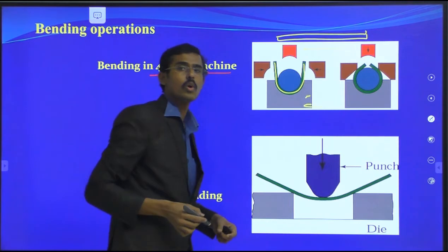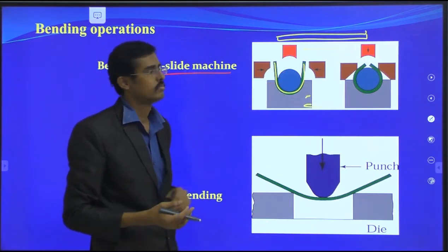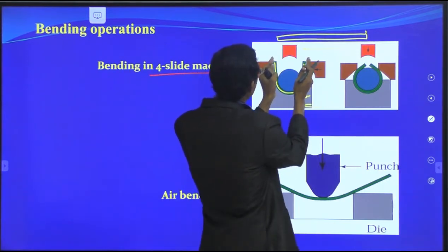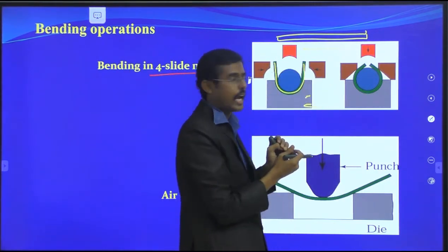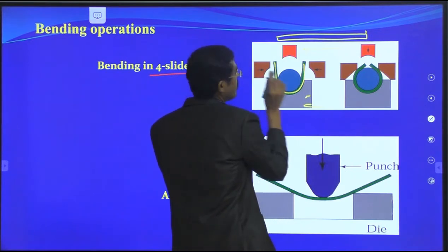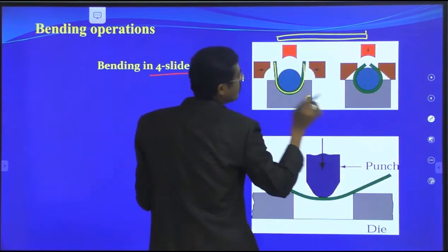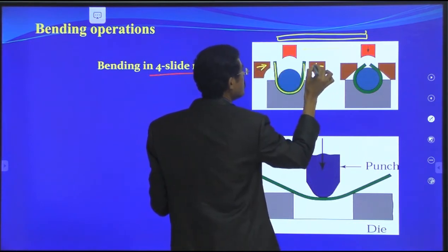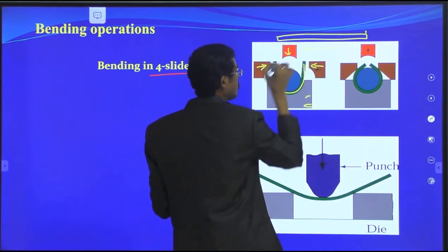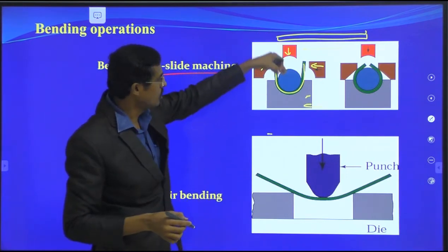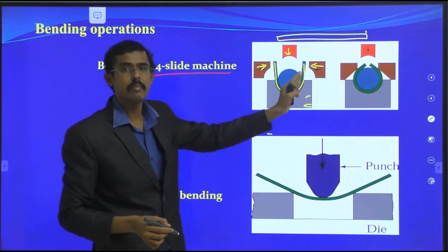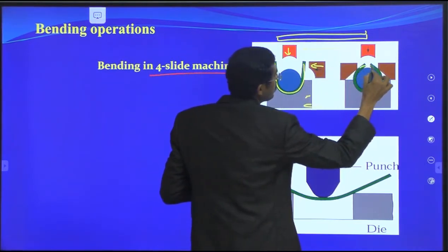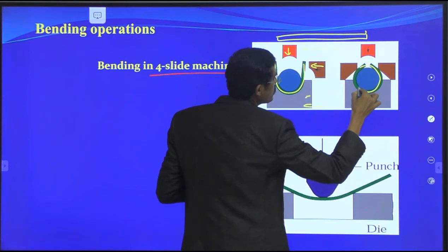First, roll bending has been done, and it is supported, or it has been punched. Here also, when it comes to this side, I want a roll. I am giving the punch here also. Force is given at these points. So what happens? First the roll bends, then the left and right bending, and again the closing bending is done to convert it into a complete circular object.